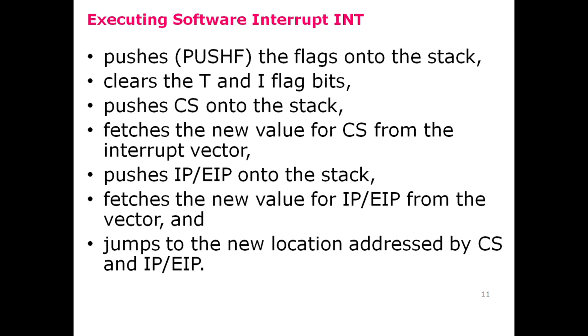Similarly, the microprocessor fetches the new value for the code segment from the interrupt vector, as I said, and pushes the instruction pointer or extended instruction pointer onto the stack, so that the offset address of the instruction that would be executed next is stored onto the stack so that it can be retrieved later on.